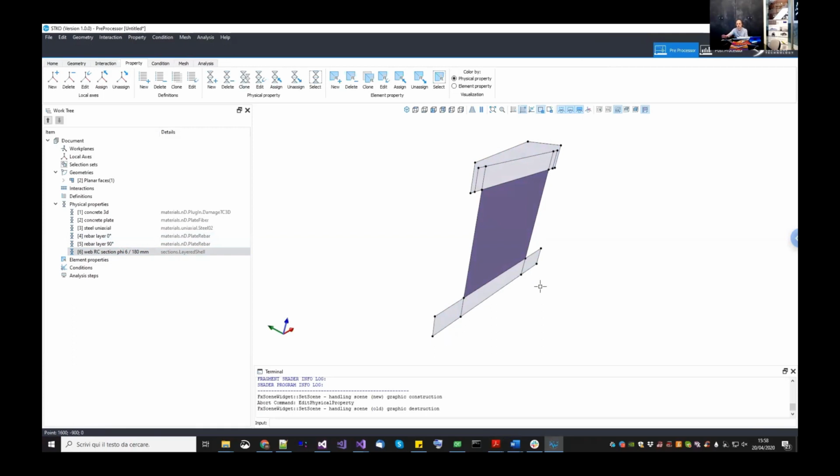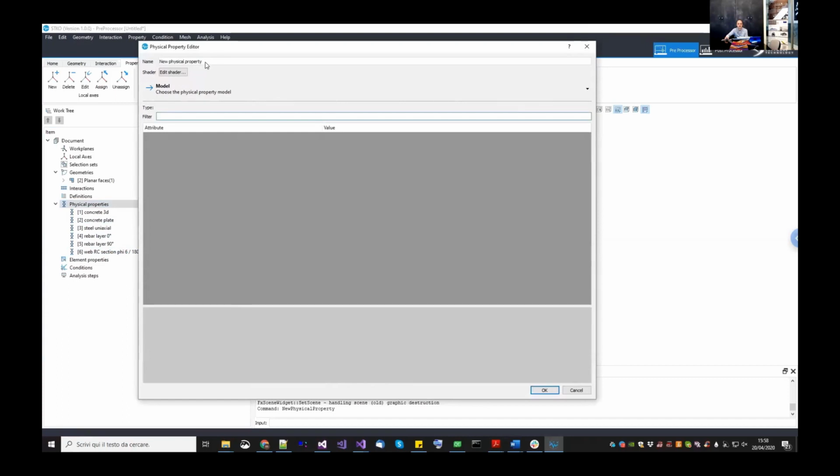As I told you, I will not use any reinforcement in those two beams, but if you want, you can change it. So the concrete is fine, concrete plate is fine. We just need to define another layer. And I will call this beam RC section, not to confuse them with the lateral beam because we are going to model them as real beams. Here I will write top, bottom, beam RC sections. There are beams modeled as shells.